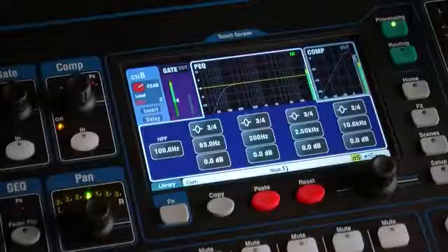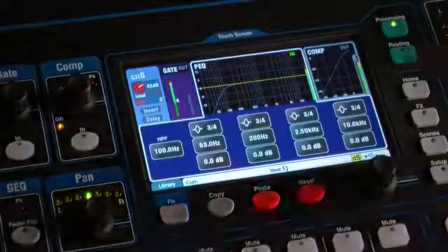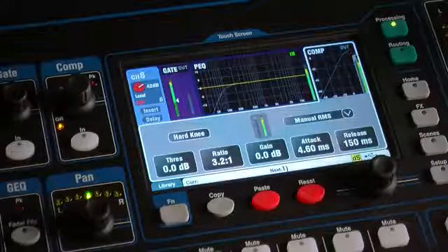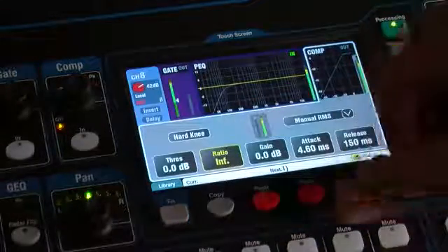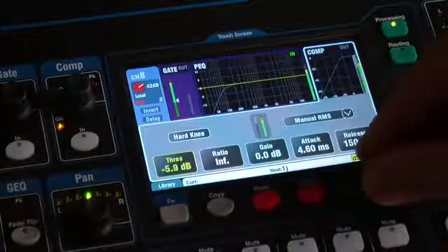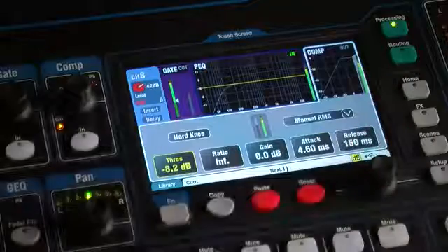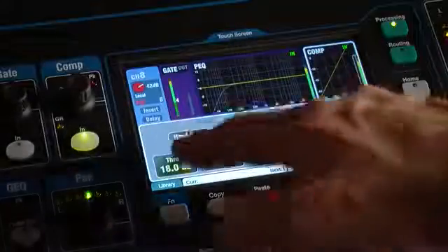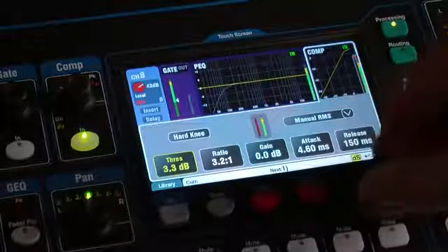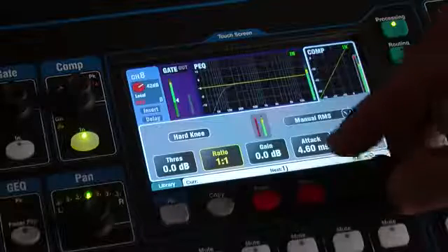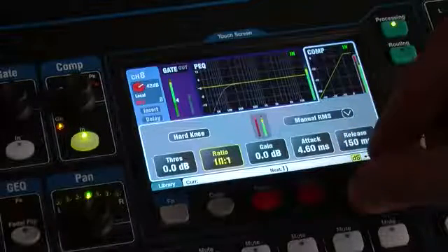The compressor is a powerful tool for controlling the dynamics of the sound, for example to smooth out a bass guitar. It works by reducing the amount of gain when the signal increases above a certain threshold. At its extreme setting it can be used as a limiter to prevent the signal exceeding a maximum level. Whilst listening to a signal, adjust threshold to set the point at which compression starts. Set ratio for how much compression you want, from none 1:1 to full limiting.